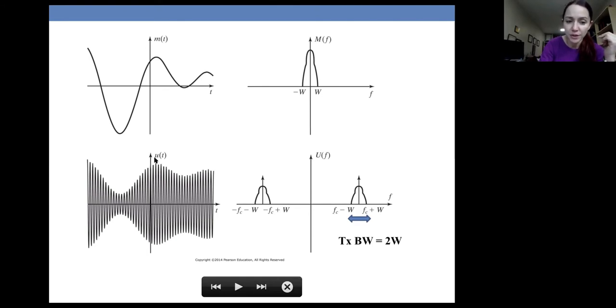So you can see the envelope of the modulated waveform looks like the shape of the message, except it's raised up. And depending on how large Ka is, whether or not the negative part is going to stay above zero. This point here is going to rise up if we make Ka sufficiently small.